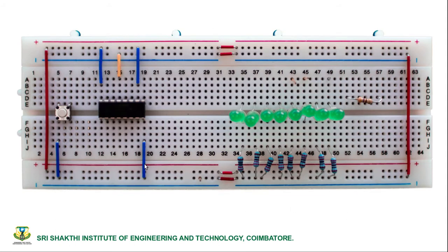See, this is how we can connect. The IC we have to connect between these, right? Here we can give jumper wires. It means this line will act as 5 volt, and this also will act as 5 volt. If you give 5 volt here, you can take the same 5 volt here.